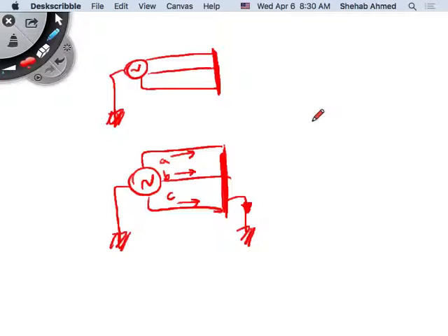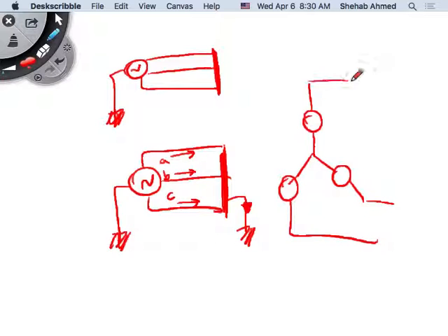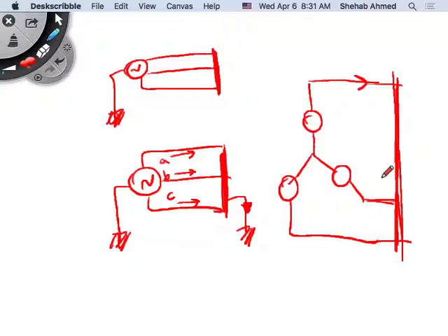What is the sum in this case? I have a generator, represented as three-phase voltages, and I have a short circuit here, right? This is what this is representing. So the current here and the current here and the current here, are they different? Assuming this is the cable resistance, R, R, R, what is the current in each of these phases? The same.